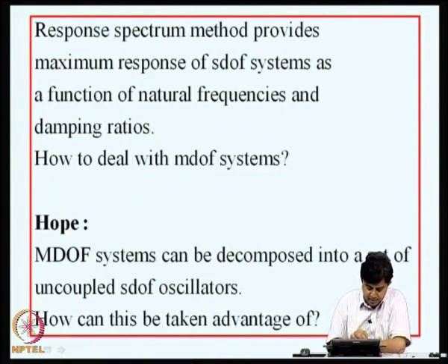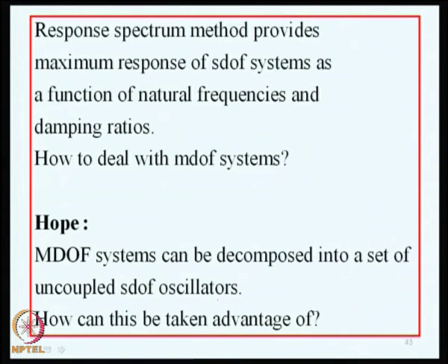that the multi-degree freedom systems can be decomposed into a set of uncoupled oscillators. So, that we know. So, for each of the generalized coordinates, using the given response spectrum, we can find out the peak values. Now, the fact that multi-degree freedom systems can be decomposed into a set of single degree freedom systems is an important advantage. Now, how best can we use this when loads are specified in terms of response spectra? That is a question we need to consider.